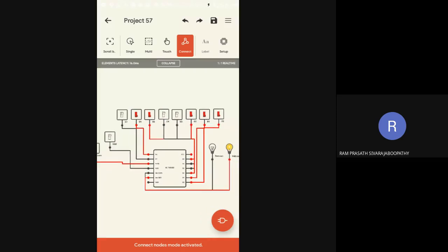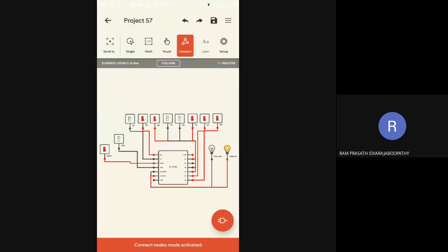So now you can see, it is now a parity checker. If you observe carefully, even out, odd out: two outputs are there. If the data I have given is even parity, even out is enabled and odd out is disabled. Now what have I given? Odd parity data. So odd out is 1, even out is 0.